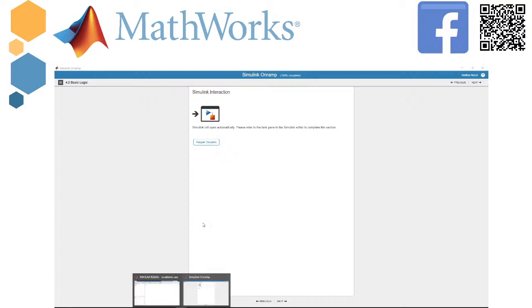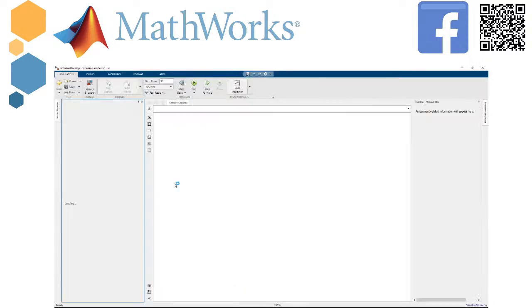Okay, so yes, I'm wrong because I put the wrong block here. Now I have compared to constant. Okay, really easy. Double clicking here, with the greater than or equal to, the constant is not 3 but 0.1. Press OK, connect it, and connect to the signal assessment. Okay, submit.